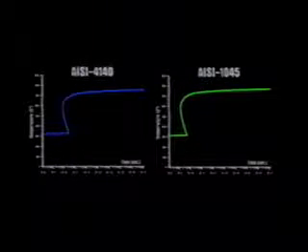Notice that the nose of the pearlite transformation is farther to the left for the 1045 steel than for the 4140. This means that it is easier to avoid pearlite transformation products from 4140 than from 1045 steel. In other words, the higher alloy content of the 4140 steel makes it more hardenable than the 1045 steel. This is why we say that the 4140 has a higher hardenability than the 1045.